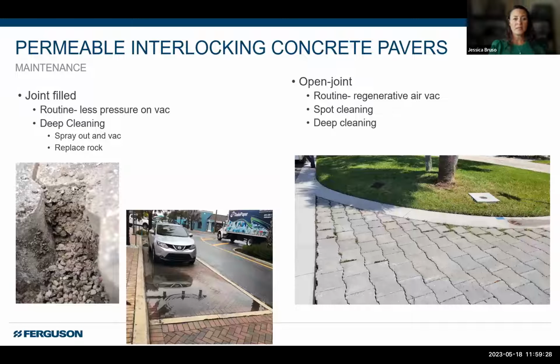Now, as far as maintenance is concerned, we can see what happens over time, right? With our joint fill pavers, we collect the sediment, which again, that's what that's meant to do. The gravel, the sand in there is meant to actually collect whatever's coming through, but then it tends to get clogged over time. This is especially true if there's going to be an organic source somewhere close to it.